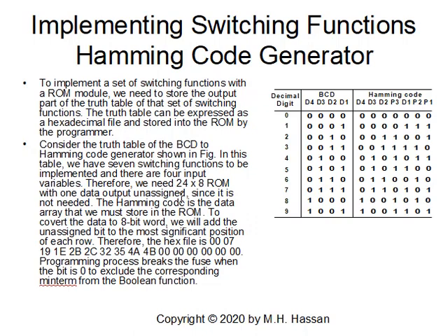Because we have only 4 input variables, we use 2 to the power 4 by 8, since 7 is not a typical number to find a chip with. So we will have a 16 minterm by 8 output ROM.